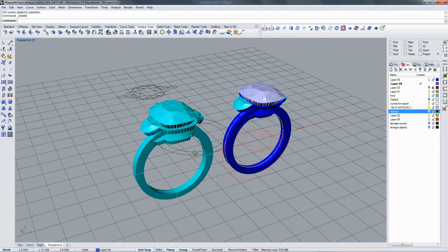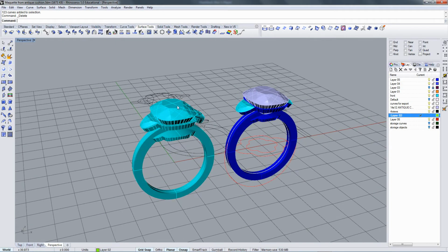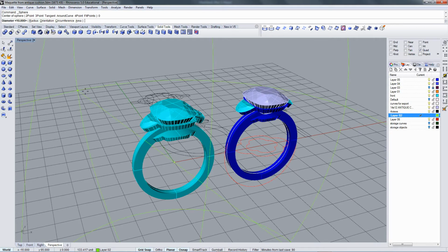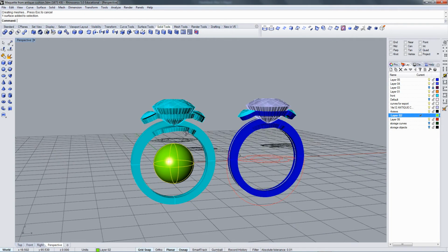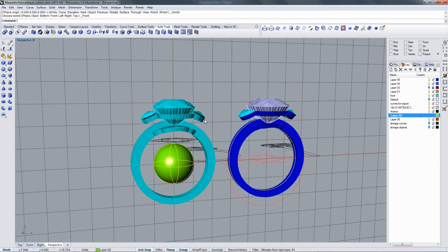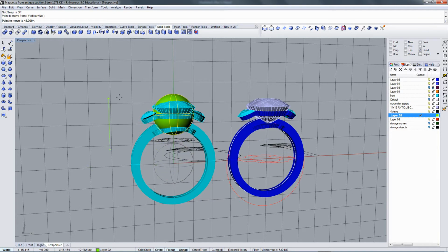And now I'm going to set up a 3/4 view that I like for this ring. Put a sphere in the center. Now I can also put the sphere, it's a tip, I'm going to do it differently this time just to keep things challenging. Once again, I'm going to put it at 0, 10 millimeter diameter. But if I do it here, it's going to make the ring bore actual size. For our purposes, the stones might be more important to have actual size. So I will move it up to here.